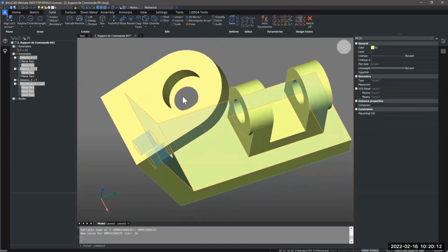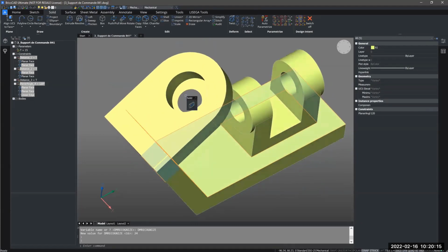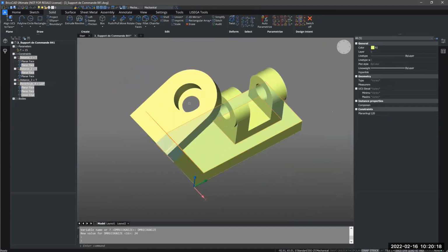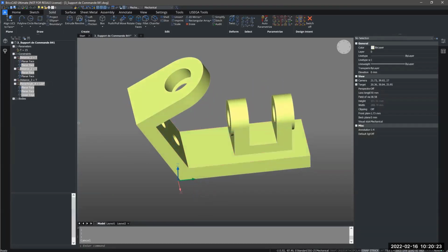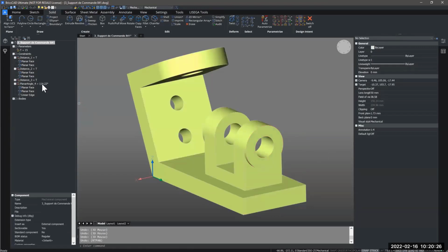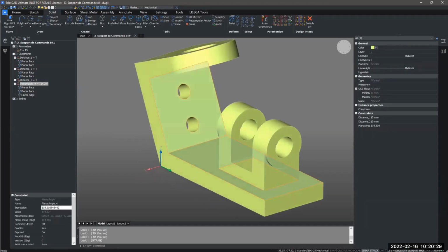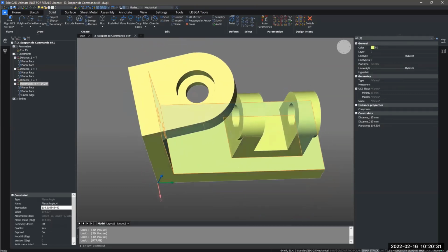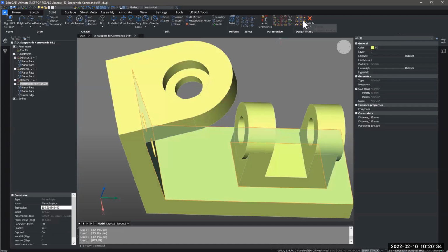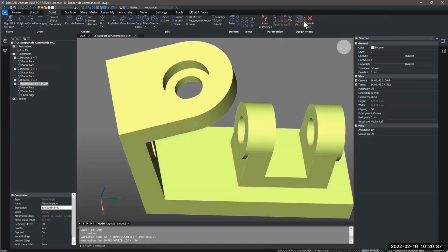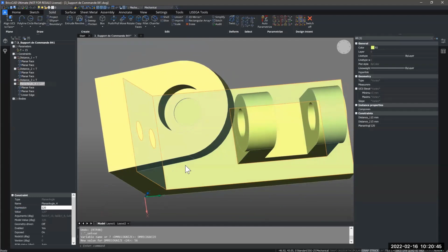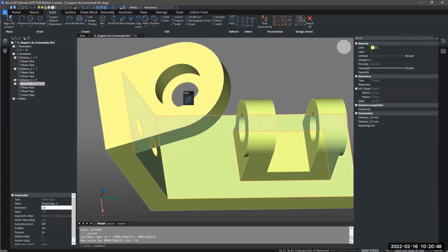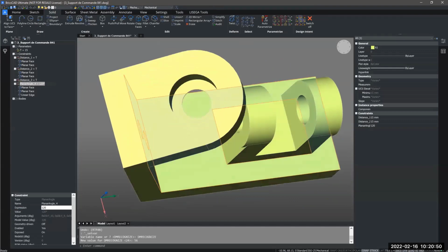Actually, you can also see that the rest of the part here moved, while the hole here didn't. However, the hole is still perpendicular. So I will once again go back and undo the value of the constraint, to keep that in place, you can see they now share the same axis. So you can also turn on the coaxial surfaces design intent. If I change the value now, it should also be sticking with the rest, and it will still share the same center. So it is now no longer out of the same center.